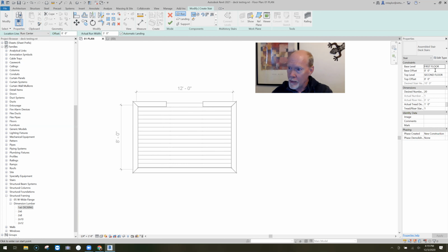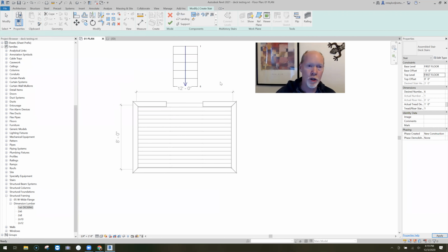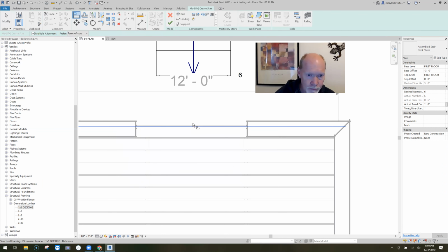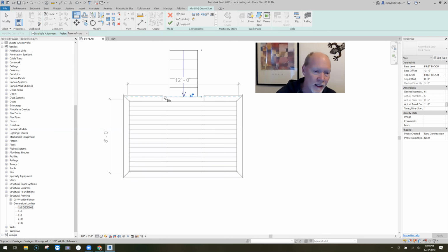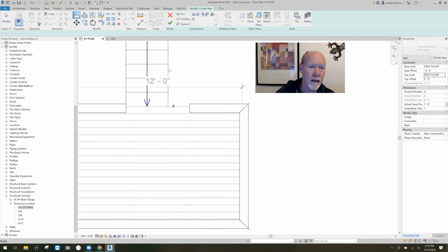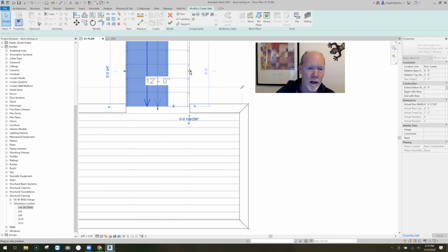The bottom of this thing is going to be -3 feet, and then the top of it is going to be at 0. So I'm just going to put this guy out here. It's out a little bit too far, right? So I'm going to use a line to go to the edge of my deck. Bring it on in. And then over here, I'm going to say align to the edge of that rail, and bring the other side over to the other edge of this rail. Right about there. I'm eyeballing it right now because it makes it easy. And check the box.